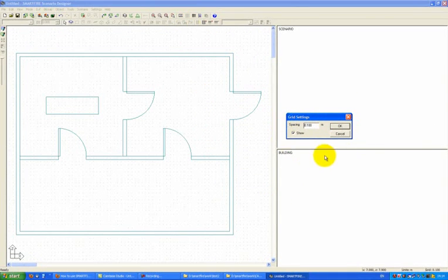The grid settings are very important as they may determine the overall cell budget. This sets the accuracy with which you interpret the lines within the geometry. If you try to interpret the lines with very fine resolution, you may end up creating very small gaps as you interpret different surfaces with a small displacement between them, and in this case you can create a very poor quality mesh. So it's very important at the beginning to decide how refined you want your mesh to be when you get to the meshing stage.